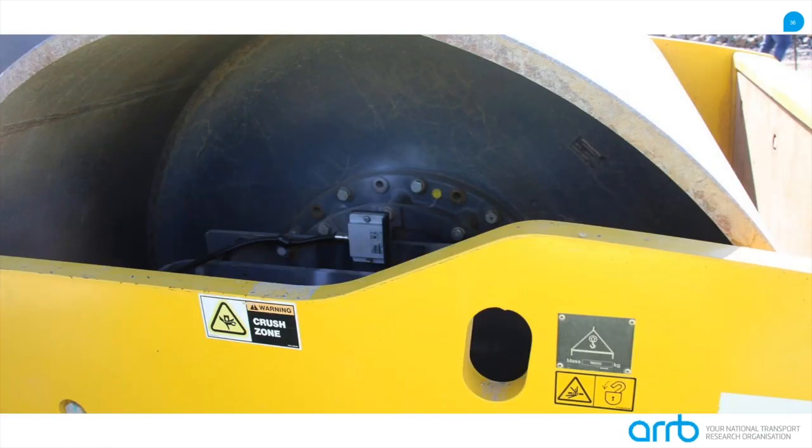And this is a close-up shot of the unit mounted in the center of the drum, where the cursor is pointing. This is the accelerometer, and to me, that is one of the essential technologies that we are using to monitor the motions. Just bear in mind, when we are adopting this technology, because we are measuring the vibration of the drum, make sure that the accelerometer is mounted in the correct position.